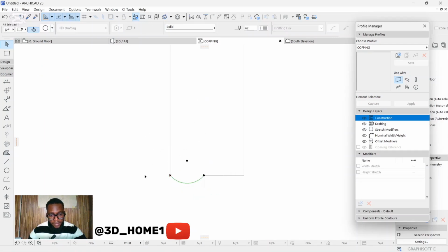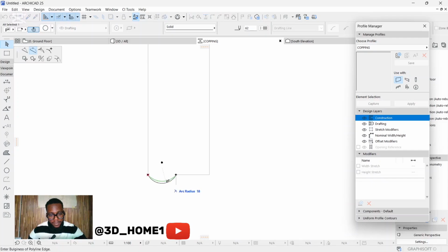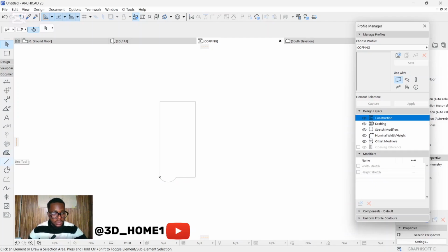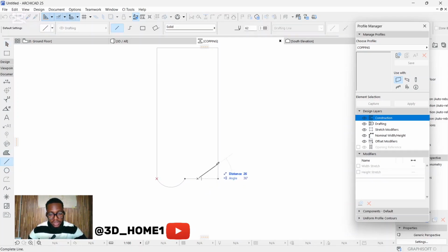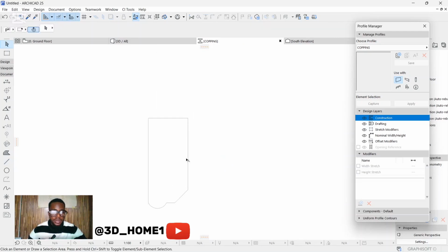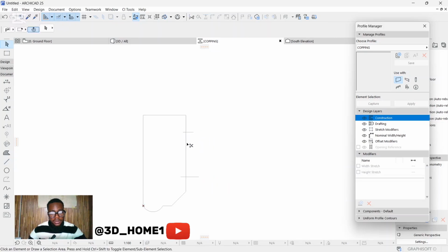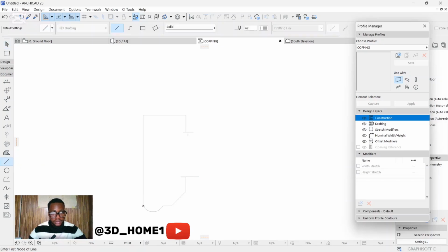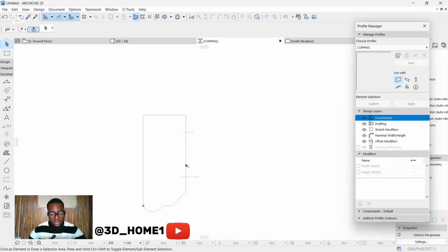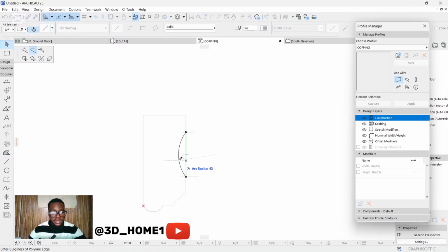Okay, clicking this point, and then this one we can decide to just chamfer it a little. So this design actually depends on what you want. And then for this middle point, you can decide to draw a line here, a line here. We trim this middle, then redraw the line from here to here again, then click on this line and then take this line inward.